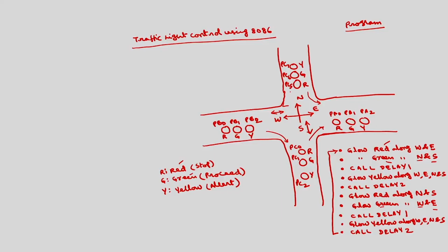Basically, here I am going to use all these ports as output ports. Here you are using port A, port B, and port C. Because you have to connect LEDs to all these ports, we have to program all the ports as output ports. Further, the instructions are: take 80H into the AL register, then out onto port A. I will assume that the port A address is FCH. So, these two instructions will program all the ports as output ports.